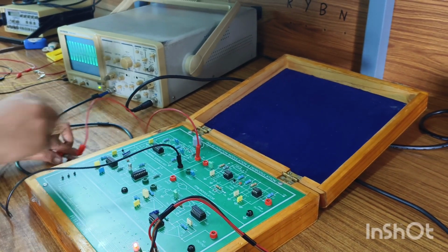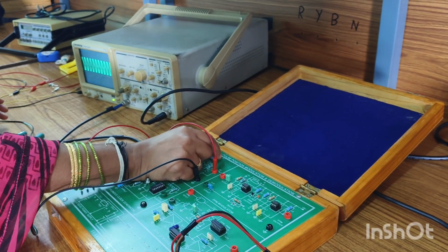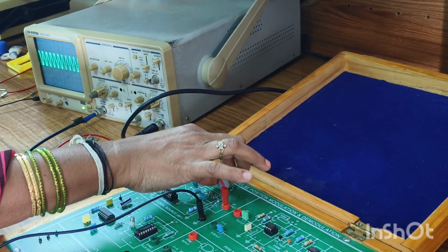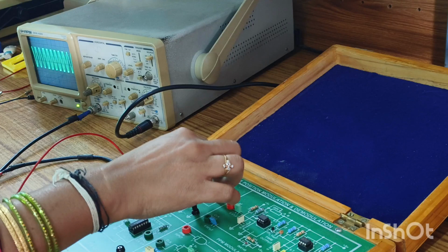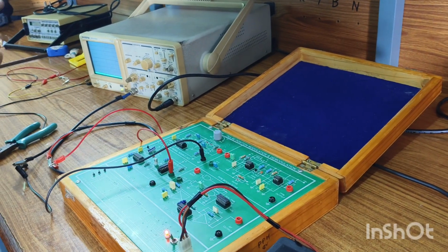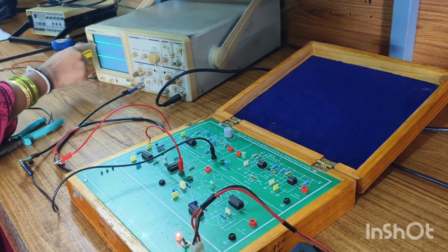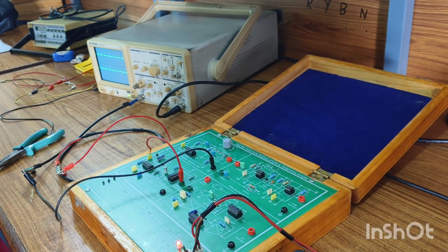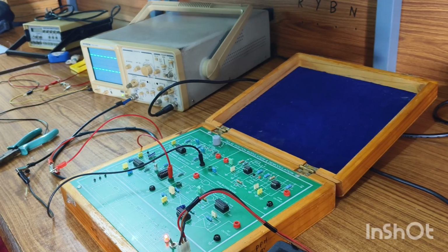See, we are getting the modulating signal or AF signal correctly. This is the amplitude knob. If you vary this amplitude knob, it is going to change. Okay. Next, I am removing this connection and checking the clock signal. See, the clock also we are getting. You need to adjust the time per division, then you can note down the time period and amplitude of the clock also.